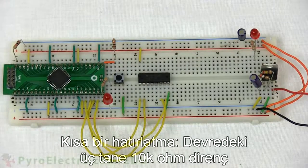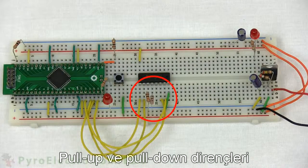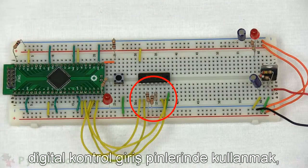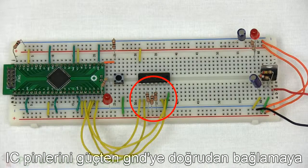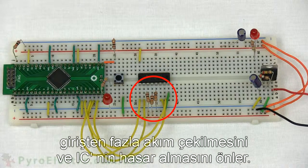A quick point here, these three 10 kilo ohm resistors don't appear on the schematic. Using pull-up and pull-down resistors on digital control input pins is good form instead of directly connecting IC pins to power or ground, because then it prevents too much current from entering and potentially damaging the IC.